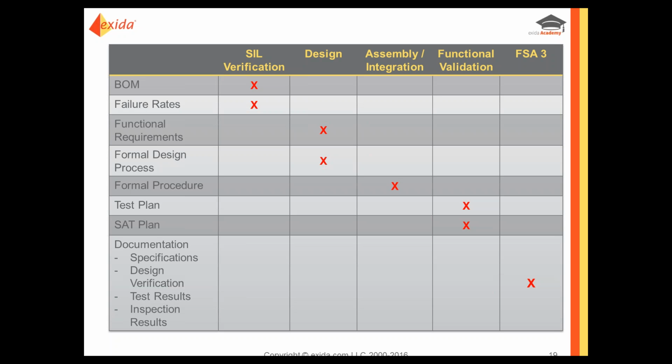There is guidance in 61508 as far as what type of coverage to claim, and you build it up from the component level, but you can have low, medium, high effectiveness diagnostics. Low is 60%, medium is 90, and high is 99. Then you need to apply that to the functional failure mode and the test. So yes, there is guidance. We've got some recorded webinars on that, and we'll be doing some more.